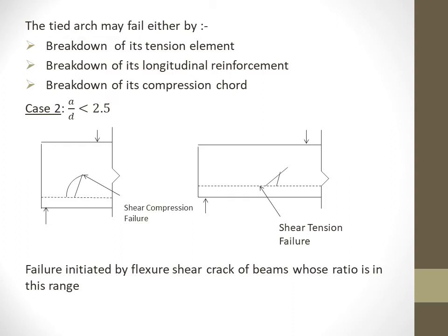Both these types of failure usually occur before the flexural strength of the beam is attained, that is the full moment resisting capacity is attained.